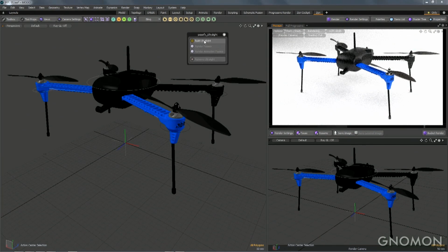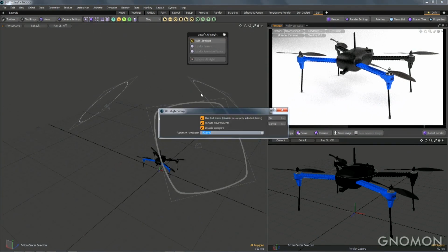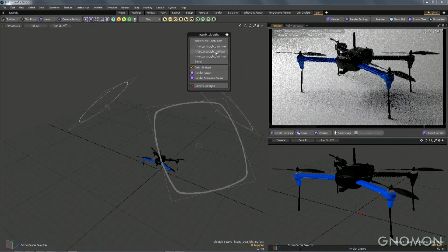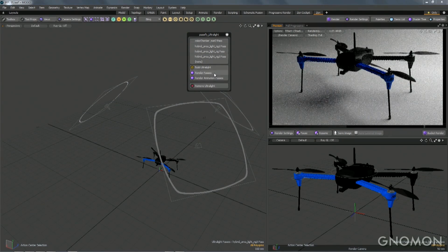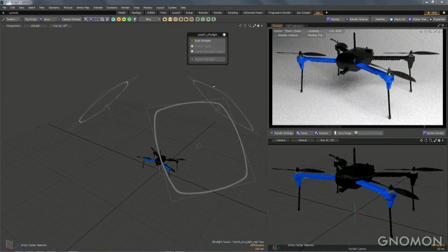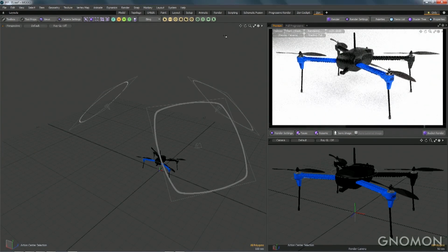Similarly, with lighting, we have one called Ultralight. Ultralight actually looks through the whole scene, finds anything that's glowing, and creates a pass group for each of those lights. So here I can turn on and off each individual light, and then of course render those out, save them, composite them in post. And if I'm using 32-bit compositing, I can do my relighting in post in real time without having to go back and re-render in Modo.